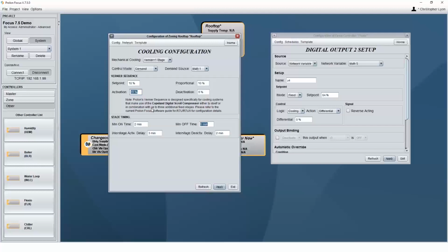And you can adjust this to whatever level you determine you need to get the oil return for your particular installation. Okay, so if I decided I needed to adjust this up to 20%, that's great. I can modulate that compressor from 20 to 100%. It will not ever at any time go below 20% other than to stop.